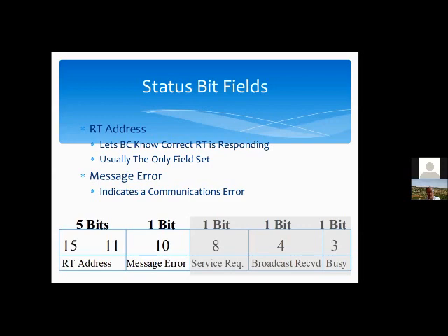And I'll go into detail what that means exactly later. But the point is that the RT would know about it and would immediately throw out the command. Any command that has an error, the RT will throw out immediately and not respond to. But there is a small but existing possibility that there will be 2 errors in a word. And if there are 2 errors in a word, then let's say, for example, the parity bit changes and the low bit changes. So instead of an RT2 in the RT address field, it now contains a 3 and there's no error in the word.